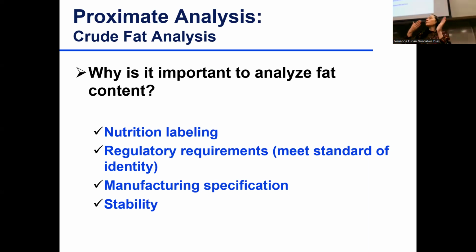For example, you have a specific standard. When you go to buy milk, you have the 2% milk. Cows produce milk with varying lipid content, usually from 3 to 5%. We standardize that to 3.5% as our full fat milk. So usually you take the fat and put it back just to be sure that everything has the same. But then you can standardize that to 2%. You can go to skim milk, which is usually reduced to 0.5% or lower.